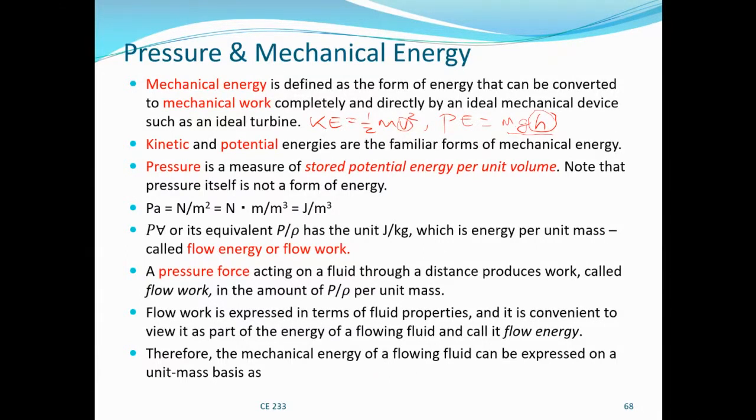I will check this slide too, because it repeats some things we did before, so I will check and edit it. So this we did, the flow energy again, which is a result of the pressure force acting on a fluid through a distance, producing work called flow work. The flow energy per unit mass is P over rho. This we explained before.